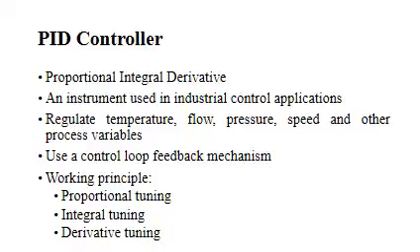The PID controller is used in some systems with a relatively low noise level in the measuring channel. The advantages of PID are fast warm-up time, accurate set point temperature control, and fast reaction to disturbance. Manual tuning of PID is extremely complex, so it is recommended to use the auto tune function.